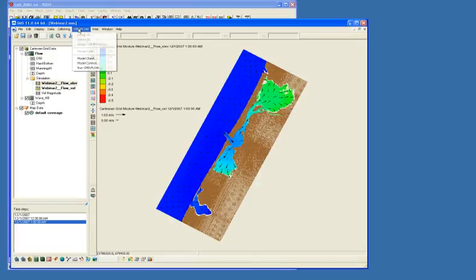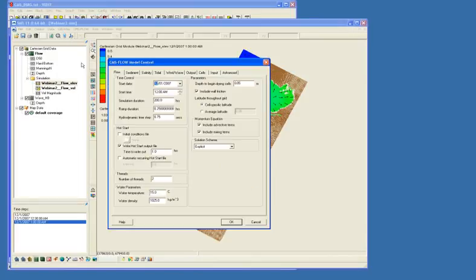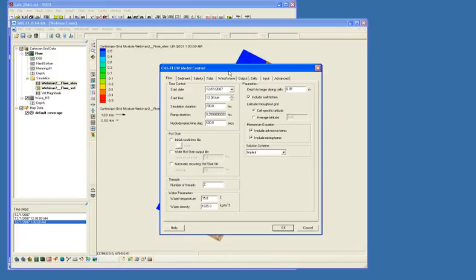And so what you can do is go ahead and into the model control, we'll change this for implicit. We'll change our hydrodynamic time step, and I'll actually turn off this hot start output file. And when you run steering for the implicit model, it writes a couple of extra card files, a couple of extra entries into the parameter file that basically says that you want to run with waves and at a certain interval.